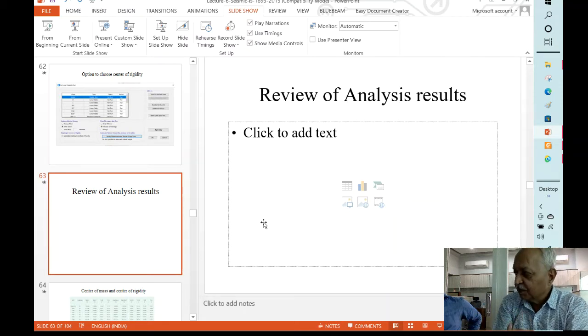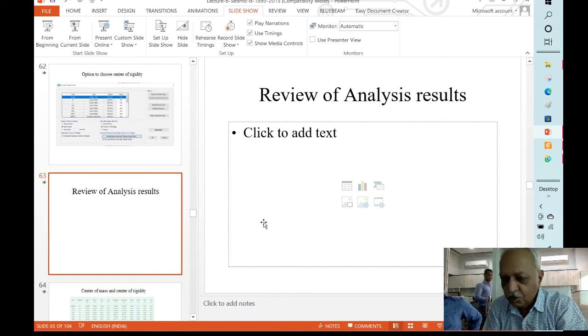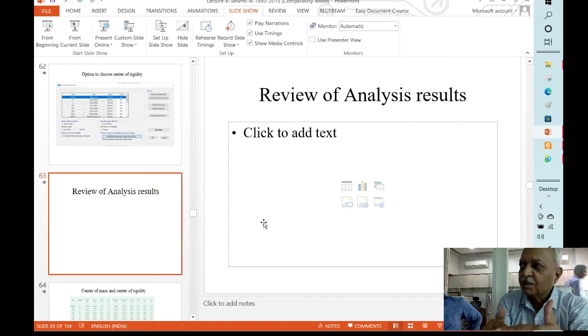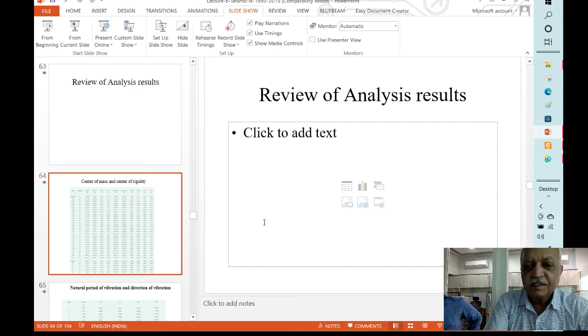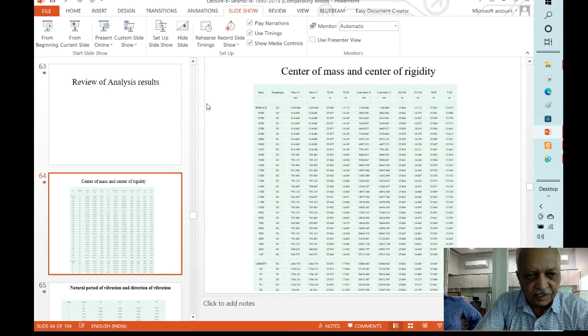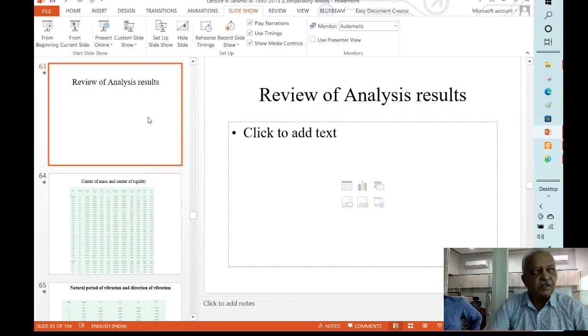If they are separated from each other by considerable distance, then you have to keep on changing the stiffnesses, because mass you cannot change. Mass is already there, it is going to remain like that. But your stiffness you can change. You can change some columns, their sizes can be changed, some columns can be added. All of that permutation and combination you can do, so that the 2 points are brought closer and closer, and when they are reasonably close, then we will say that the torsion will be avoided and so on. Okay. So this is now some substance of preparation of data.